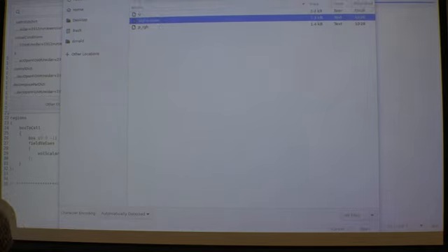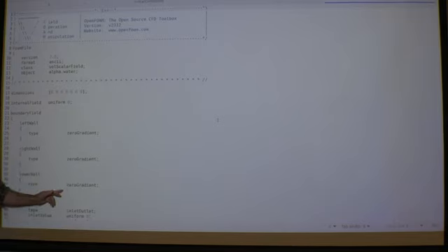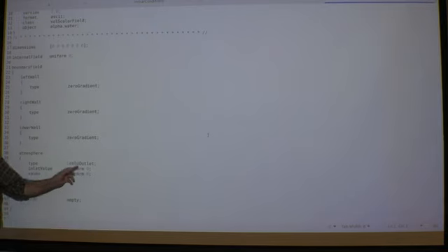And then we have a variable, our alpha. So this is also going to be a flow variable or field variable all over your computational domain. And yes, it's dimensionless. So it's just a number between 0 and 1. So here we have the boundary conditions for this alpha. Left, right, lower, these are going to be solid walls, so that's not a problem. But the top wall is actually an atmosphere, open to the atmosphere. And then flow may go either in or out, depending on how the simulation goes.